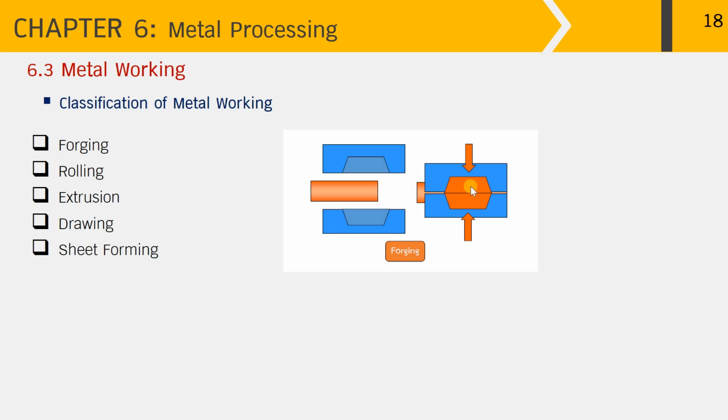Once this lump of metal has been forged by applying the normal force against the die, a small amount of the metal flows out through the flash, while the inside die cavity is completely filled to give the final forging product. For the rolling process, the metal slab is rolled from left to right to reduce the thickness to the desirable size, and this is through a set of rolls that revolve in opposite directions.